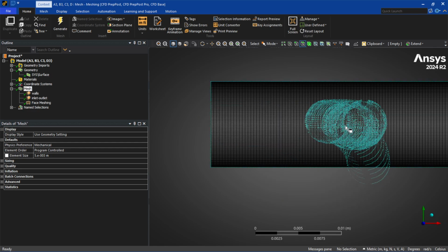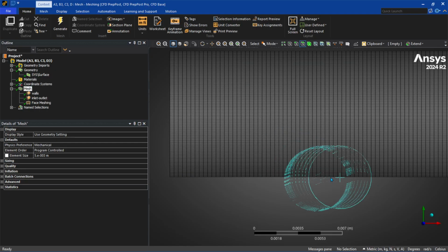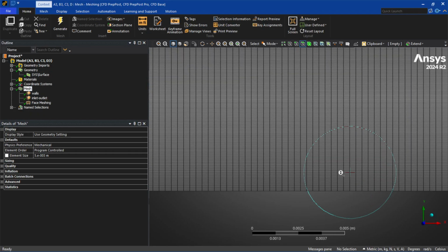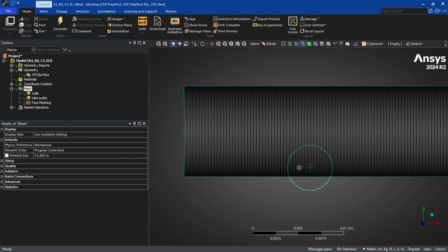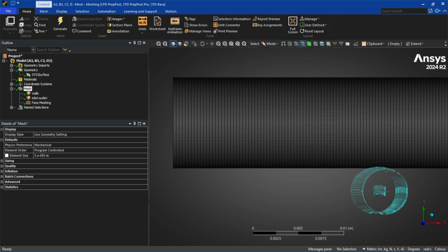The center here is a little bit coarser than the edges right here. You want more focus near the edges, closer to that boundary layer, because that's where you get all your drag forces and all your forces. Although this time we're not going to really be focusing on our forces, it still is pretty nice to focus more on the boundary layer. It's just great practice.